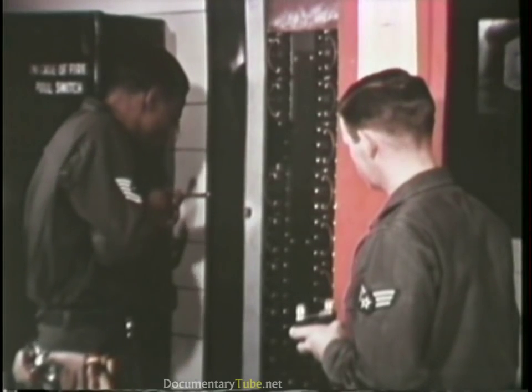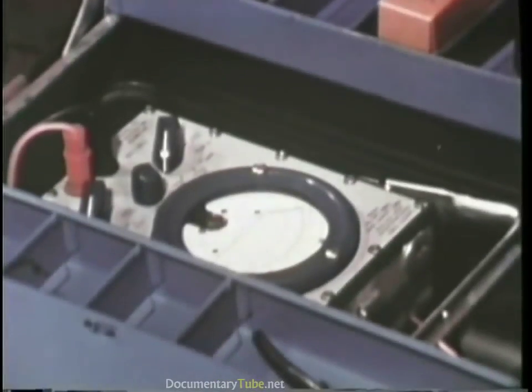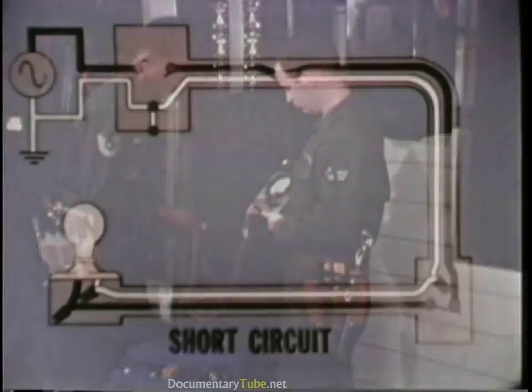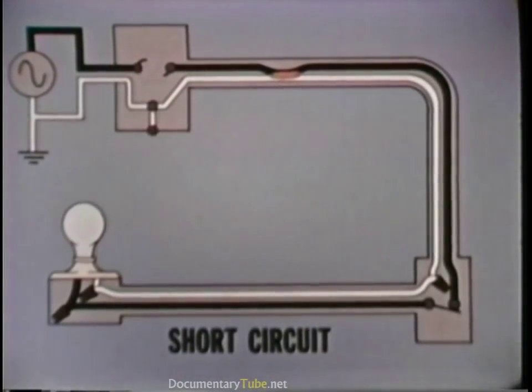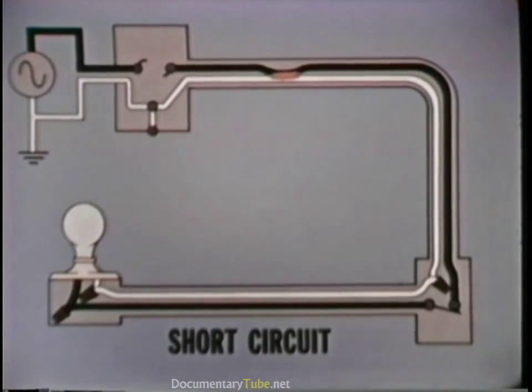The tools normally used for troubleshooting are a voltage tester and a multimeter or buzzer-type continuity tester. We will demonstrate the use of these tools to troubleshoot this familiar basic circuit. The protective device has been set off, indicating that the fault is probably a short circuit or a grounded circuit.